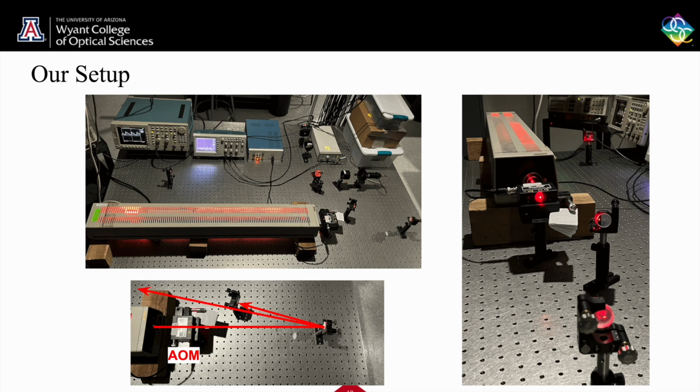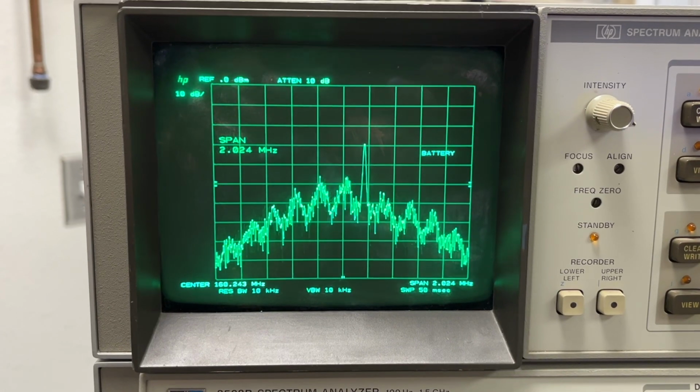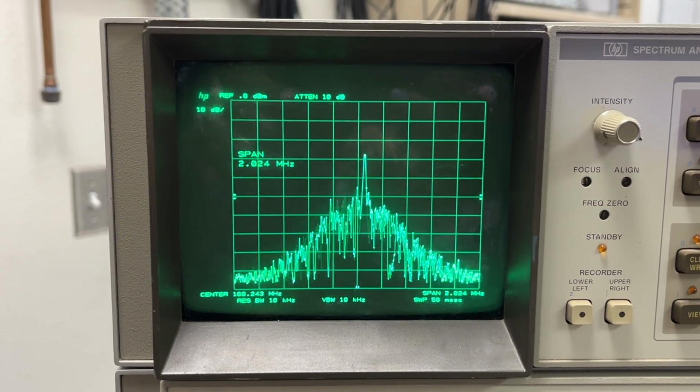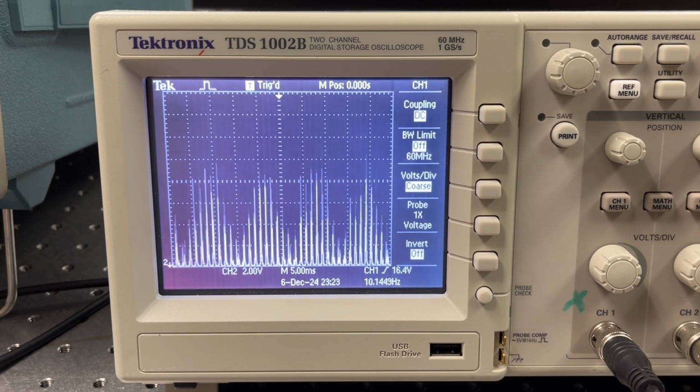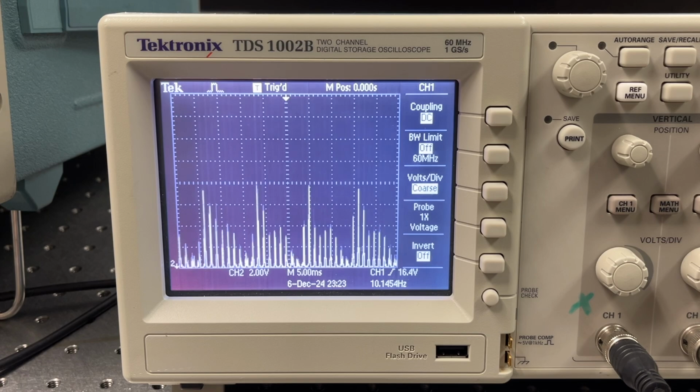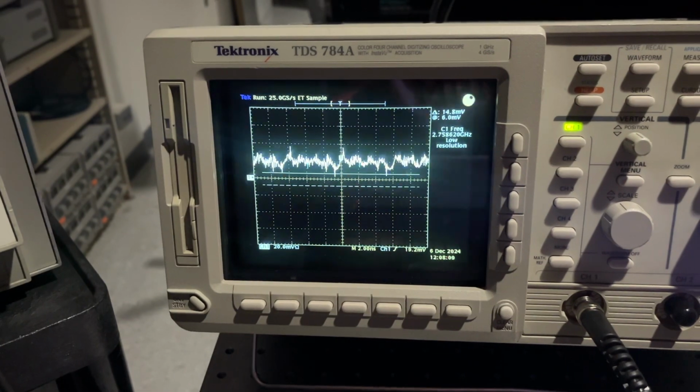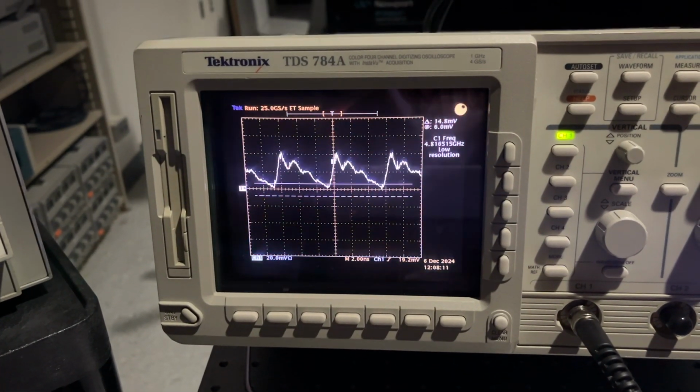When all criteria are met, the electrical spectrum analyzer will display the interference frequencies converging to the FSR frequency when we adjust the AOM phase shift. The oscilloscope will show the mode fluctuations disappear and lock down to be in phase with each other. The fast scope will show the actual pulse duration and shape.